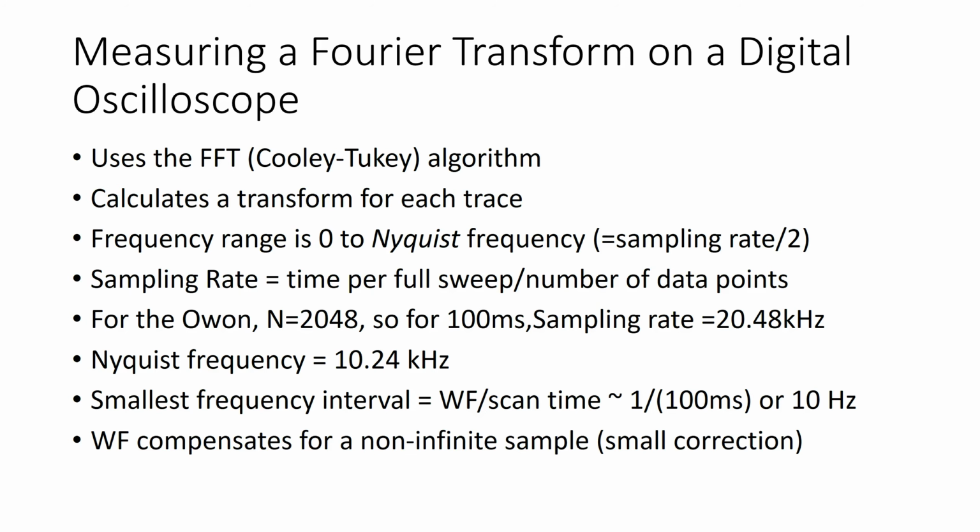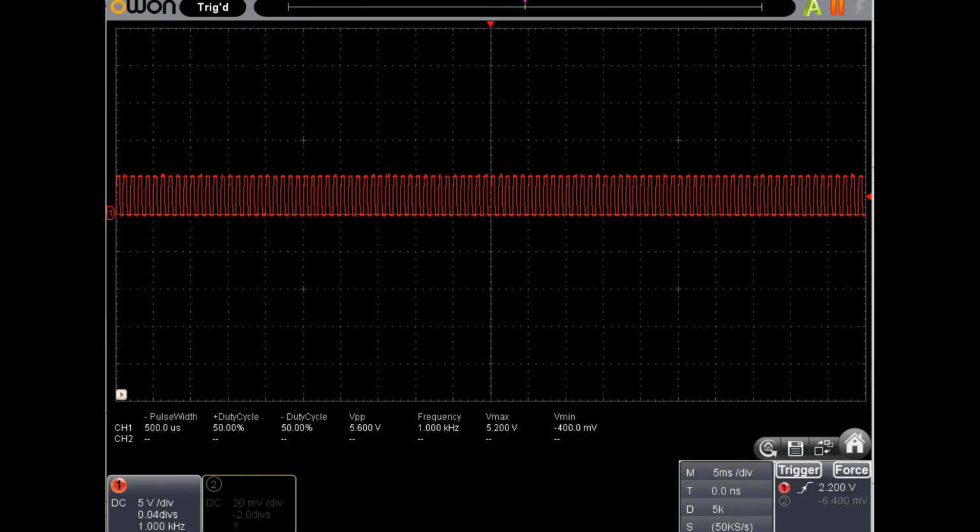Okay, so now we know what to do. Let's do the lab. This is the simplest lab you have in the whole course. All you need is our friend the O1 oscilloscope with the scope probe for channel 1 attached to the 1 kilohertz output, and let's see what happens. Okay, our trusty O1 oscilloscope is booted up, and we have connected the probe for channel 1 to the test pin with the 1 kilohertz 5 volts peak to peak output, and you see this now displayed.